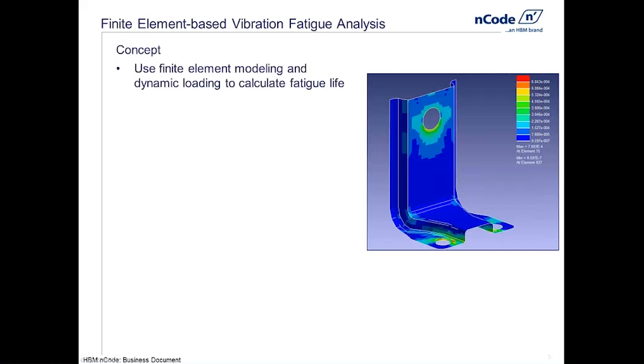Okay, what do we have to know? The idea is that a finite element analyst can use modeling in dynamic loading to understand fatigue life. If you think about this as a block diagram, FEA should tell us how loading becomes stress. Then loading turning into stress becomes a stress history, or a list of stress or fatigue cycles or something like that. And then from that we can calculate fatigue life. So that's the idea. We want to leverage the stresses we can get from FEA in order to extend our structural analysis past statics into fatigue.